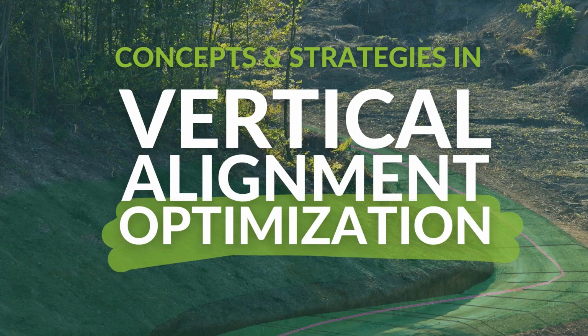So today we are going to focus on concepts and strategies that you can use to leverage vertical alignment optimization. Vertical alignment optimization is part of our Softree Optimal add-on, and it's a way of minimizing the costs and earthworks for a particular vertical alignment. I should say in particular, the subgrade construction costs.